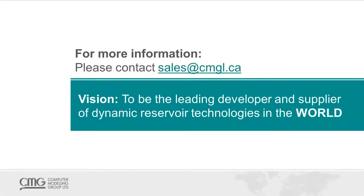The next question is from Richard Omake, and the question is, is it possible to model flocculation kinetics in an asphaltene precipitation model? Yes, actually, as I mentioned, in GEM, you can capture the flocculation mechanism that happens during the asphaltene deposition. There are a few parameters that you will define, then GEM will model it and will capture the mechanism involved in the flocculation.